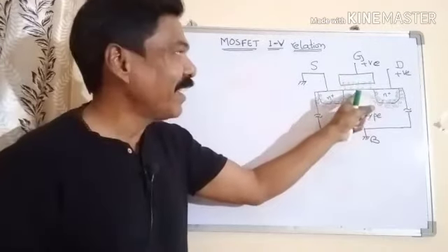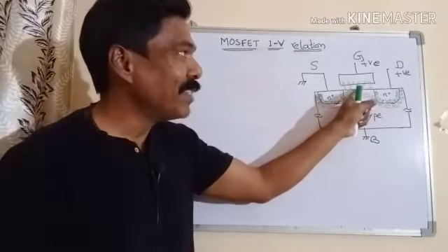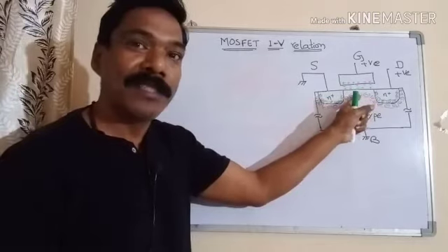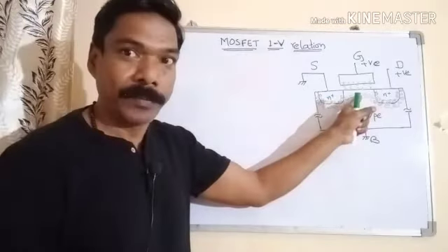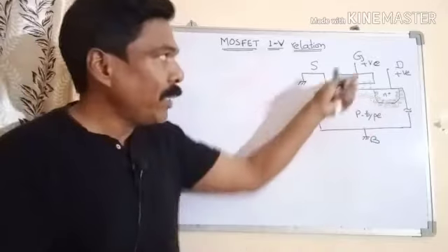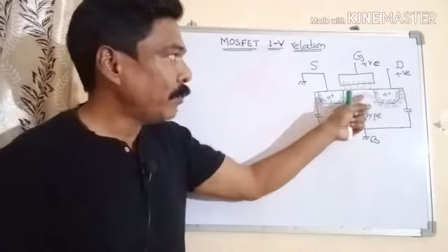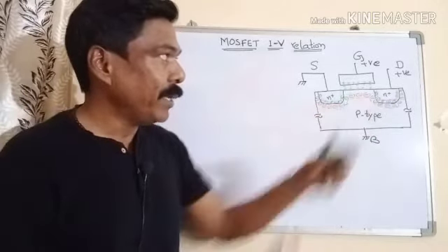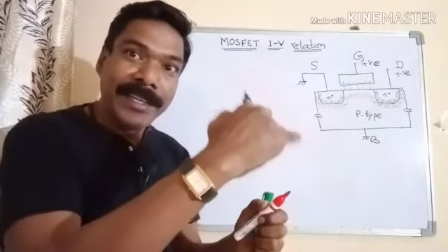It is acting as a capacitor, and the positive charge in the dielectric is being balanced with the immobile ionic charge. As you keep on increasing the gate voltage, the mobile charge will keep on depleting, and the surface potential will be slightly lowering.